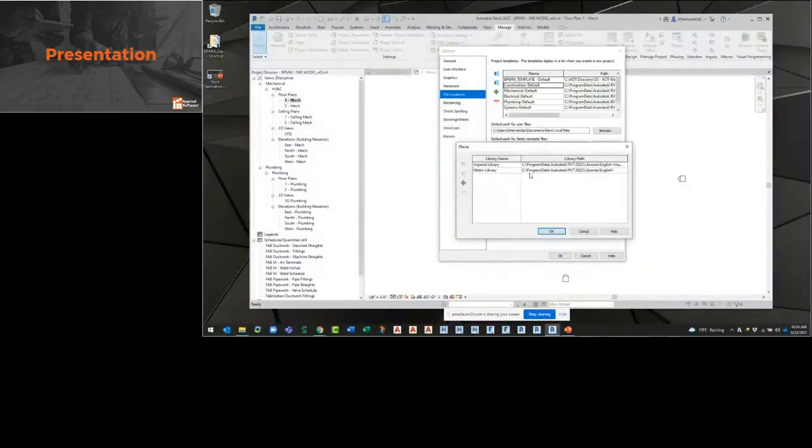So when you're in a template, you don't want to overload your templates with too many families. Say you've got 1,000 variations, you want to use single types, maybe not one family with 100 types in it. Try to split that up if possible, if they're custom families.